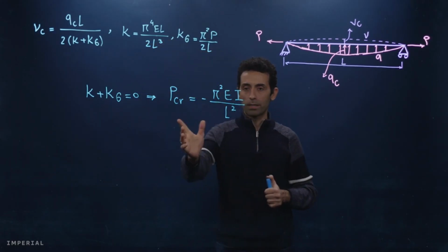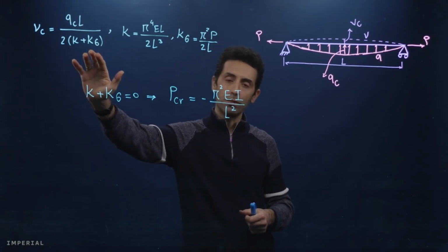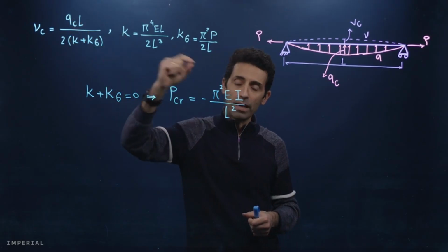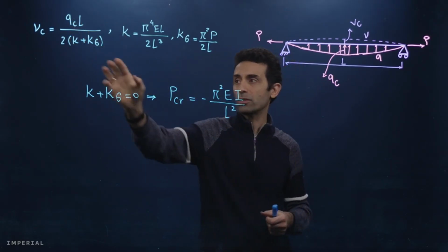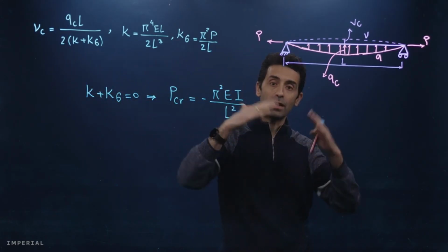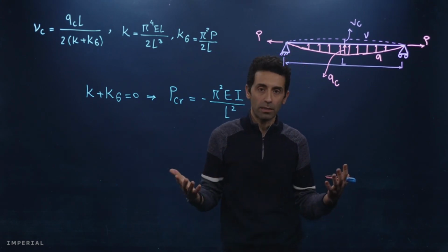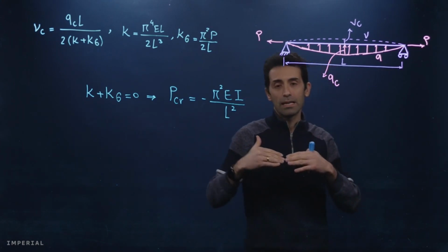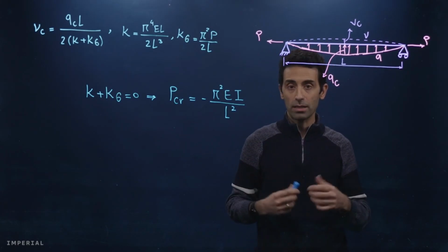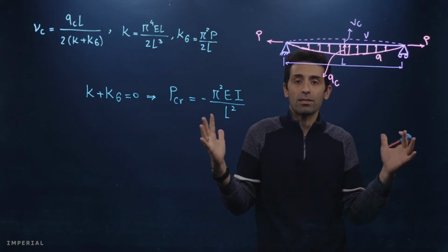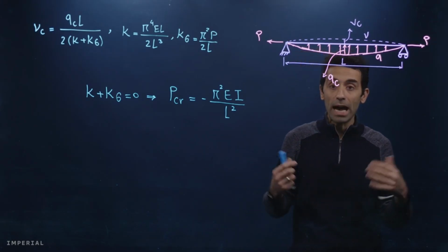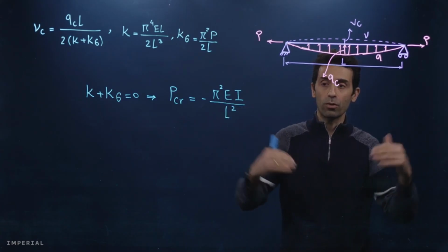So this is actually really interesting. Mathematically, you have a denominator that is 0, and that would mean that even if you have a very small amount of lateral deflection, you can produce a very large, maybe infinite, theoretically, value of lateral deflection. This is buckling, right? As we described, buckling is when stability is lost under these membrane, these axial compressive forces or stresses, and then this axial energy, or membrane energy, is transformed to bending energy without increasing that axial force or stress.